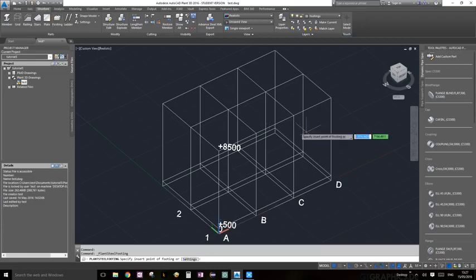So you're going to click on the footings, and once you click on it, as you can see, it's going to ask you to specify the insertion point, but we haven't defined what the size of the footing is. Every time you make any kind of choice or command on AutoCAD, the command line at the bottom is always going to give you extra options. So always make a habit of reading it.